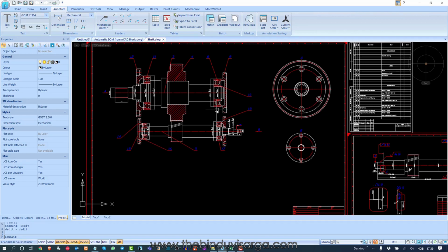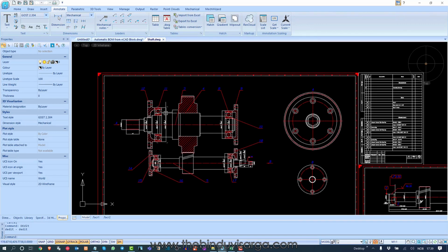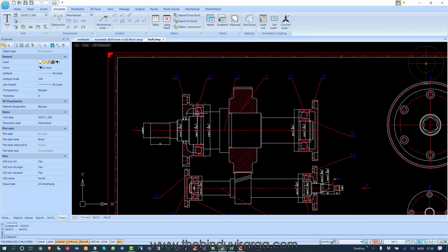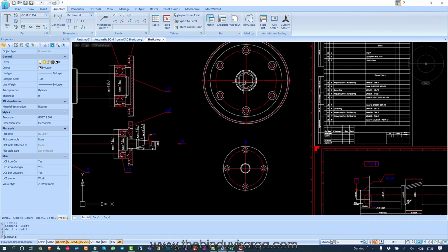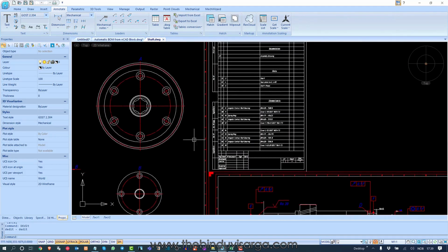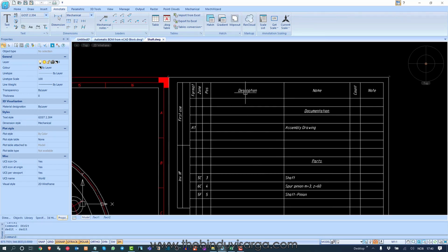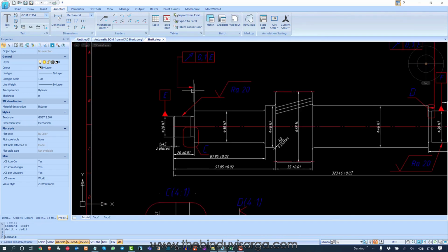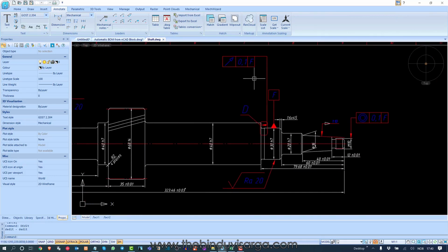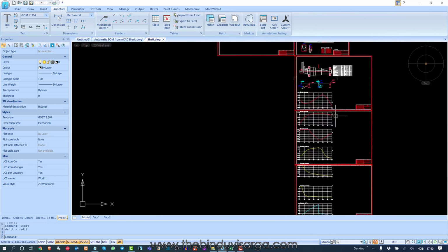This one. And now we will try to create some object-based report. As I already explained, we will see how we can create an object-based report in nanoCAD Mechanica, right? So this is one assembly we have, and there are different views, and we have the part list BOQ here, and we have some detailed drawing, and we have some very useful annotations and some testing results.